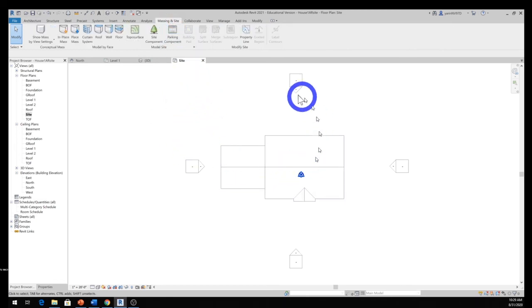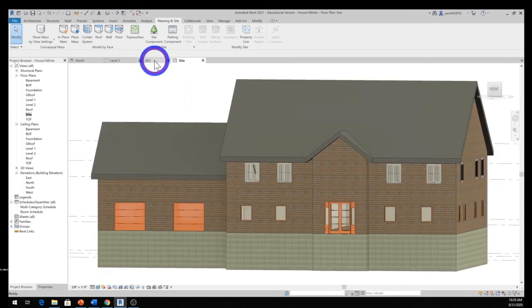Okay, and then we want to put in topography here. As you notice, if we look at the 3D right here, it's not a good idea to walk out of this door. That first step is about 9 feet deep, and it's not going to feel good. So we're going to make maybe a couple of steps here. And in a garage, when you drive your vehicle out of the garage, you want to be at the same level. So let's take care of that.